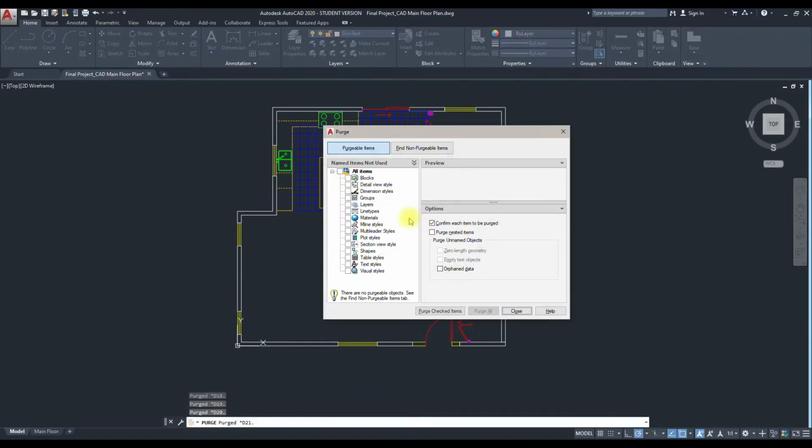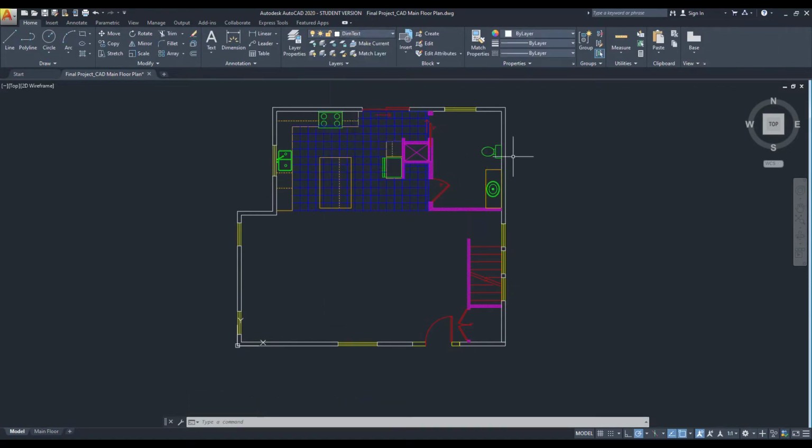Moving all the CAD entities to the origin at 0,0 will help the import come in accurately and prohibit viewing problems later in SketchUp.